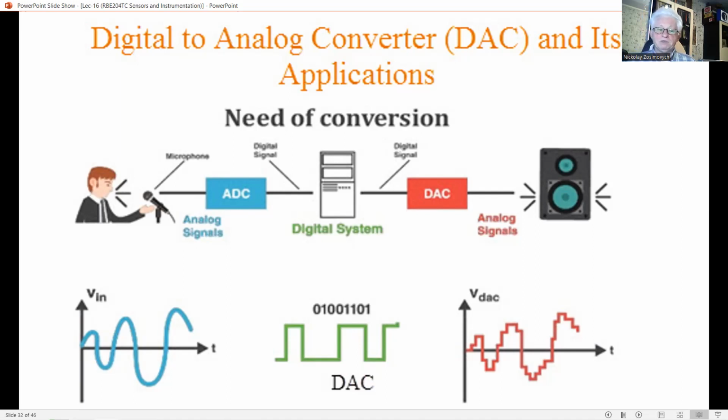Then, the purpose of the DAC is to generate an output voltage or signal level that has this numerical value and maintain the value until the next digital word in the arriving digital data sequence is converted into the analog form. Since a voltage output cannot be arbitrarily large or small for practical reasons, some form of scaling would have to be done in the DAC process. This scale will depend on the reference voltage that is used in the particular DAC circuit.